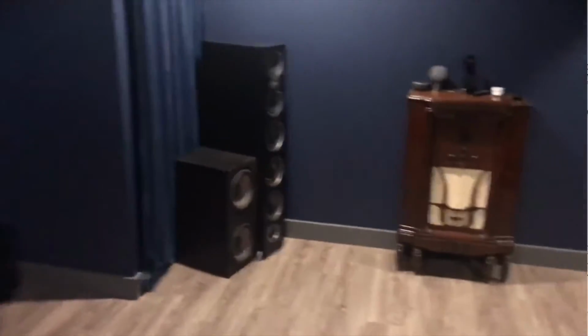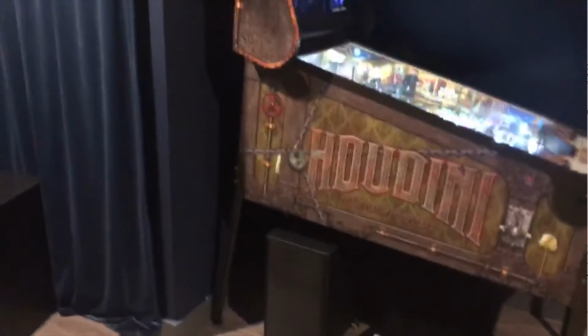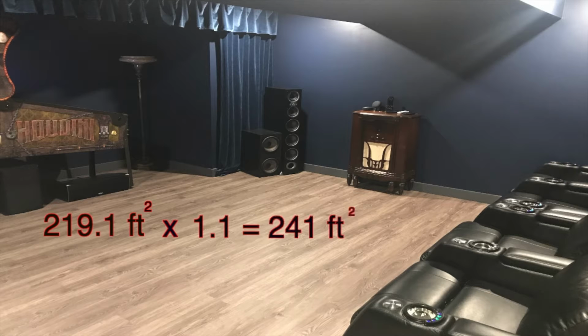Now the contractor knows how much flooring material will be required for this room. Flooring contractors usually add an extra 10% to what they calculate they will need, so they have extra material on hand for the job. In this case, the 219.1 square feet would be multiplied by 1.1 to represent adding an extra 10%, resulting in an area of about 241 square feet of flooring material required.